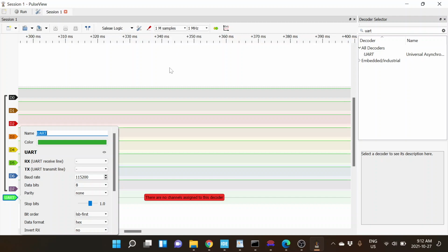And one of the things, if I'm not seeing stuff on the line, like I currently am not, is I have to go back and look and say, it's not seeing any transmission. Why is it not seeing any transmission? Has the UART been enabled? Is it actually sending data out? That's the kind of thing. So right here, I'm going, well, I was sending data out yesterday, but I'm not seeing anything on here. So why am I not seeing anything?